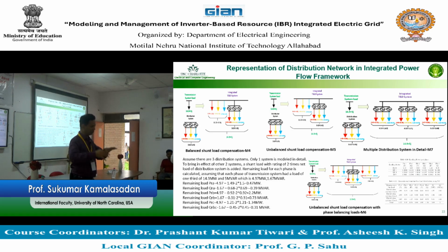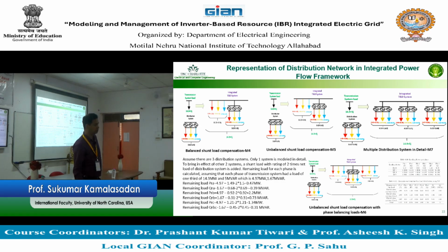Or you can actually add a shunt reactor. So physically, you can do the same thing that we are doing in the modeling world. In fact, if you increase the dynamics and you do more, depending upon how they're unbalanced, you can also do reactive compensation using power converters. It may be FACTS devices or even the inverter sitting at that point. So that approach is flexible with respect to time. You can actually adapt based on it.